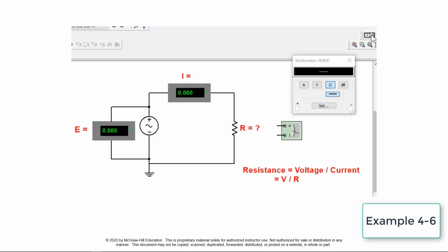The resistance value is verified by switching the power to the circuit off, connecting the ohmmeter across the toaster element, and observing the resistance reading of the ohmmeter.